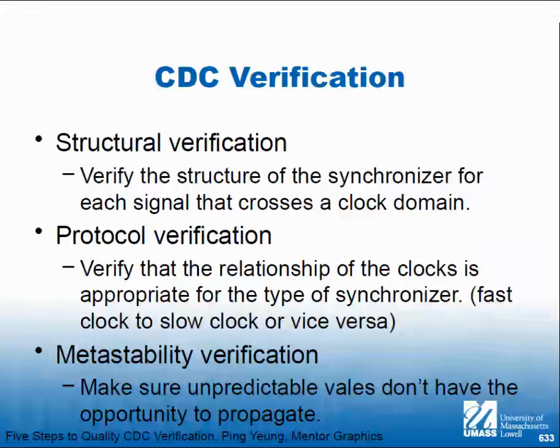It's on a push button. That push button is completely asynchronous to the design, to the clock. So someone says, well, yeah, but the interrupt can happen at this place or this place. But the problem is, if the interrupt actually sees a metastable state, that metastable state goes into the state machine of your processor and puts it into some odd state. It crashes, right? So the protocol doesn't work.